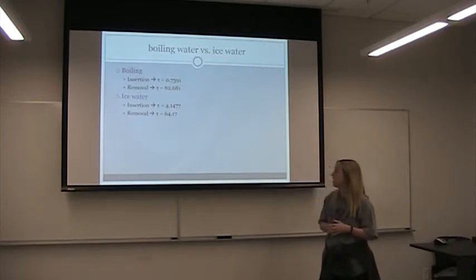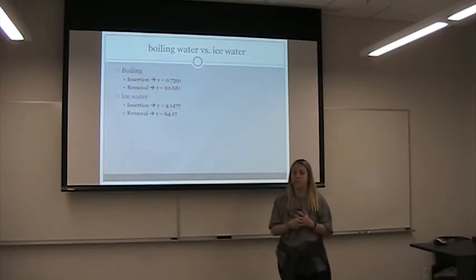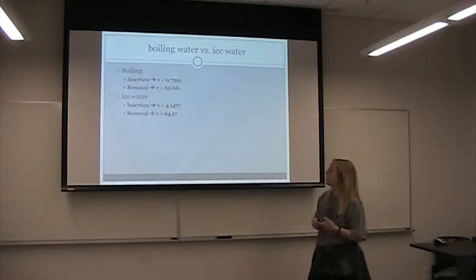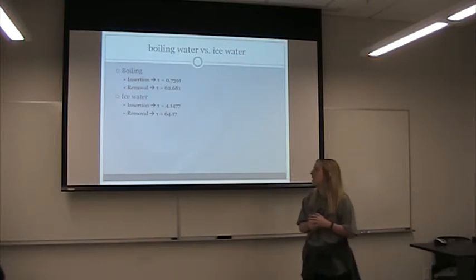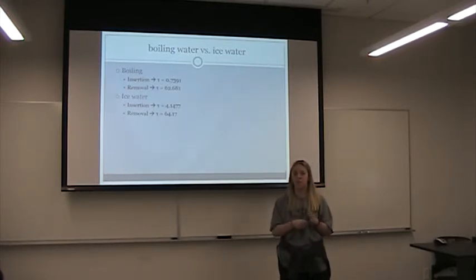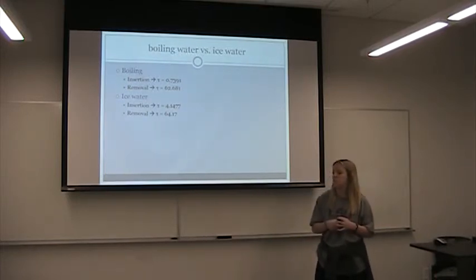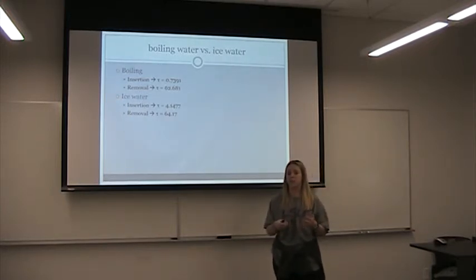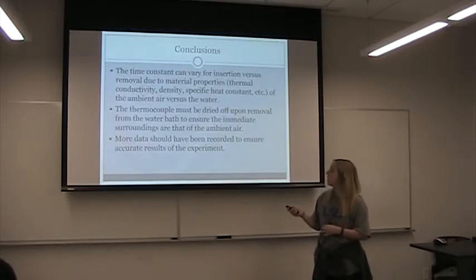We compared it against the ice water, which was, they got 4.14 for their insertion and 64.17 for their removal, which, as you can see, the insertion is a lot smaller than the removal for both cases, and this is because the density of water is a lot higher, so that plays a role in the heat transfer coefficients and the time constant. And with that being said, putting something into water is going to transfer heat a lot faster than taking something and just putting it into the air.